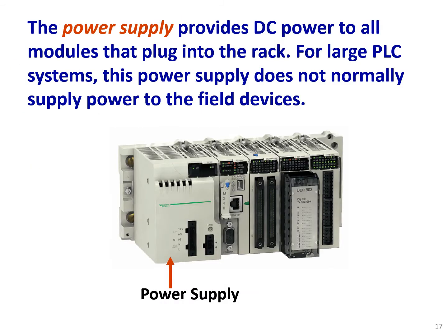The power supply provides DC power to all modules that plug into the rack. For large PLC systems, this power supply does not normally supply power to the field devices.